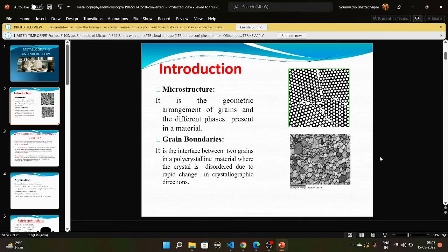Yes, sir. So you know the headstock, tailstock, and the tool post, etc. On the tool post, when you are setting that cutting tool before the start of the actual machining process, as you know, our requirement is that the tool material should be harder than the job material. Now when you place this tool on the tool post, it projects out of the tool post like a cantilever.